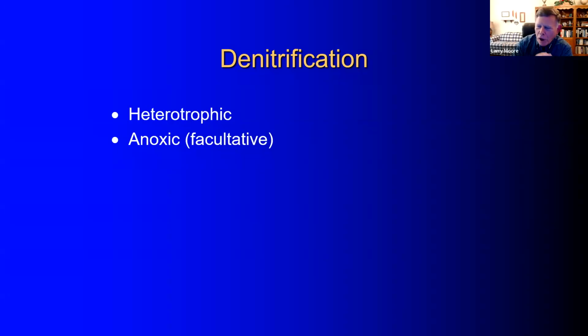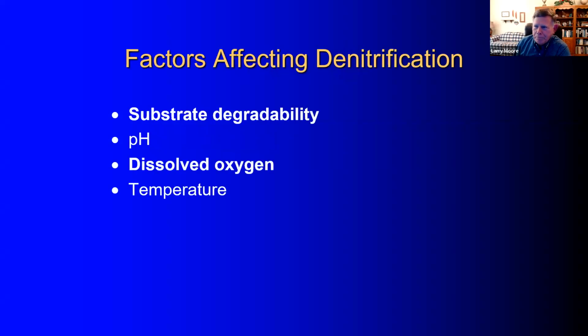And again, we're going to allow the oxygen to preferably go down to 0.0 milligrams per liter and force those bacteria, take away the oxygen. They're going to look next for nitrate. And if nitrate's available again, they're going to operate in the anoxic mode. And so we're going to manipulate the process to try to achieve energy efficiency and denitrification.